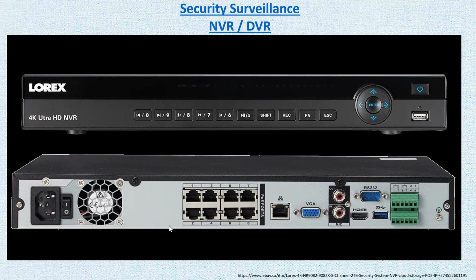Okay. Now, you could plug in to the network. So you can plug this in right to the network, and you can plug in a switch to the network. But then you have to start programming things. You have to start assigning, you have to search for the IP addresses of the cameras. So sometimes you can detect the IP address on the camera, or sometimes you have to just take the camera and look at it.